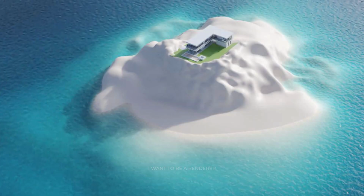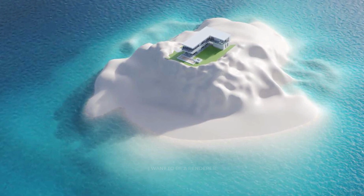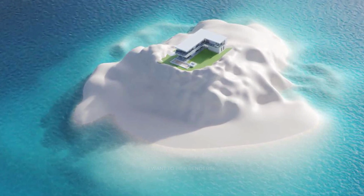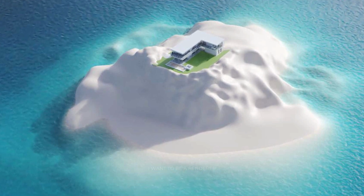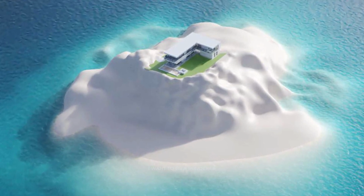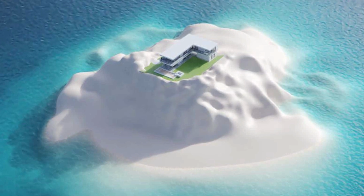He used two basic models, one plane for the ocean and the other the seabed and the island. For the modeling, he used Blender's sculpting tools, with dynamic topology turned on so he could see where to put more details and where not, and started sculpting. He also sculpted the bottom of the sea a bit to make sure there are variations in the color of the water. Finally, he got rid of the hard shapes with the soft brush, set his first camera angle, and